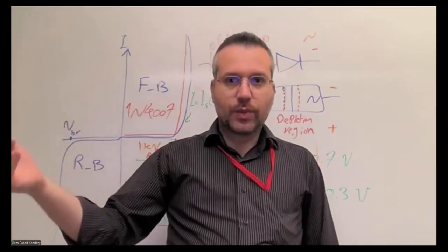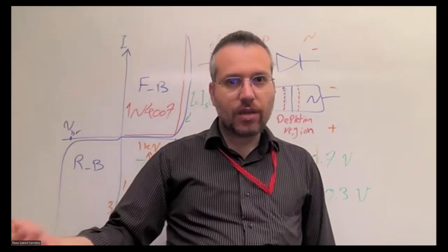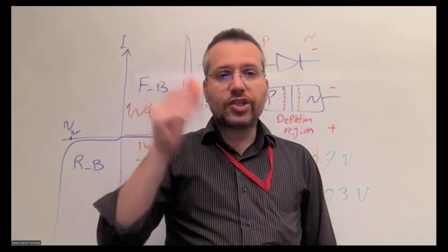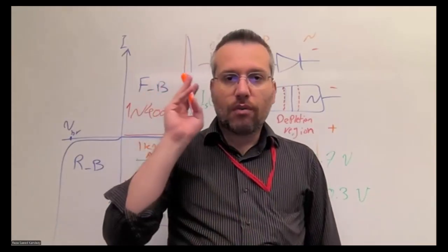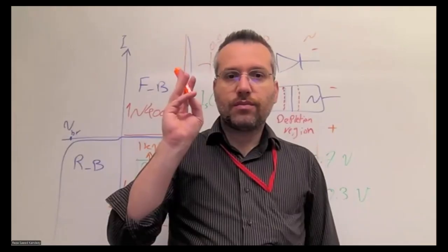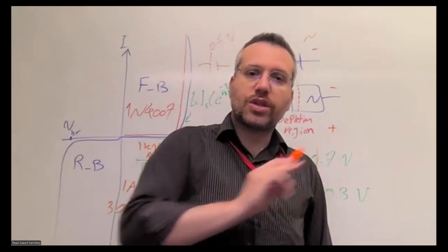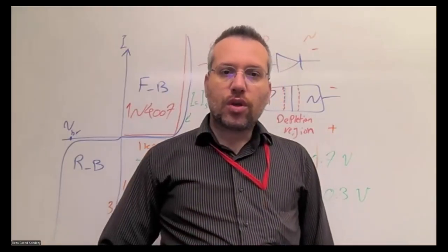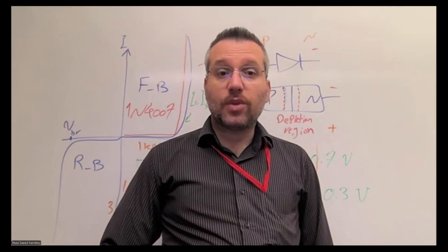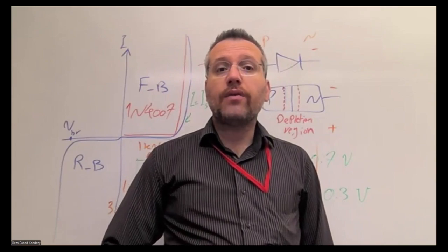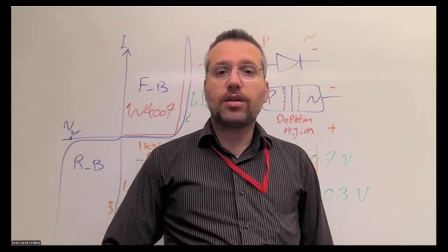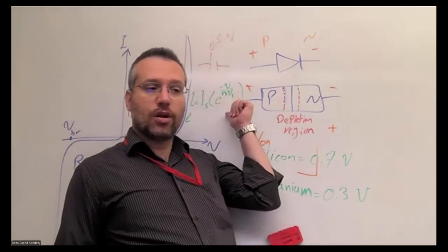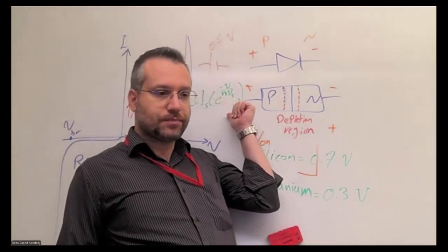In silicon, it is 0.7 volt. In germanium, it is 0.3 volt. You have to always check the datasheet for maximum ratings before building your circuit. After this, we are going to go through some simulation to simulate the IV curve and plot it so we could confirm it is actually an exponential function.